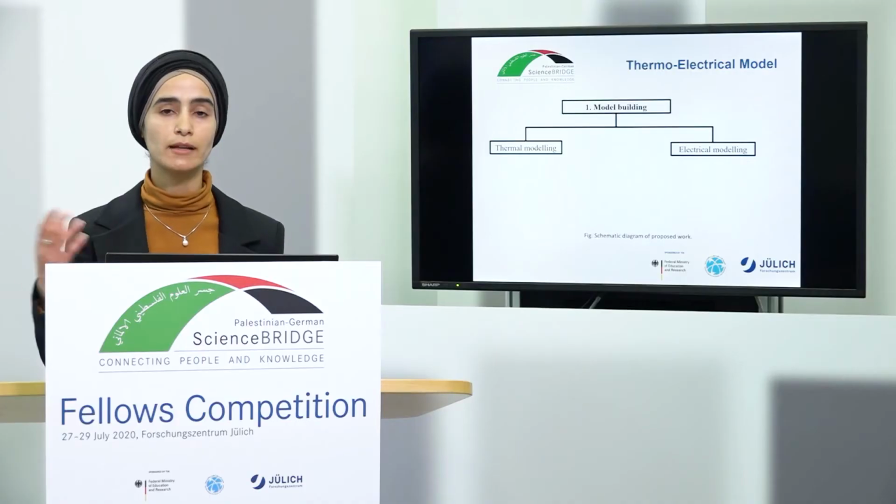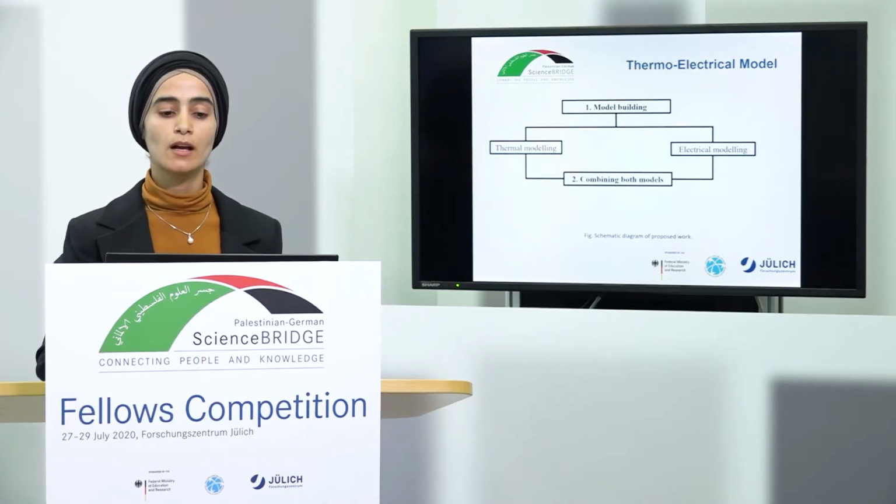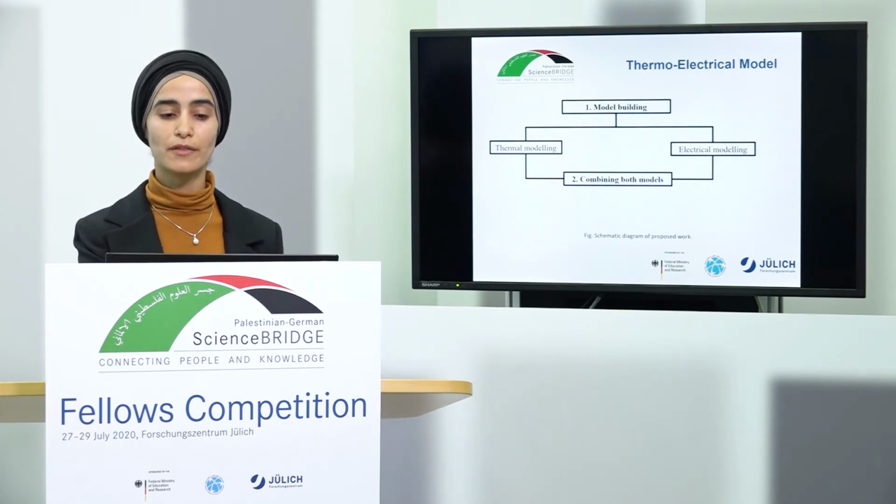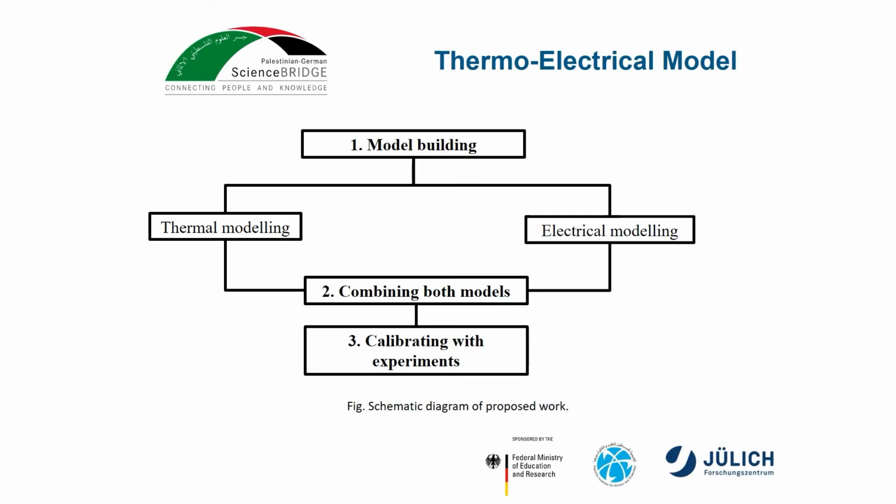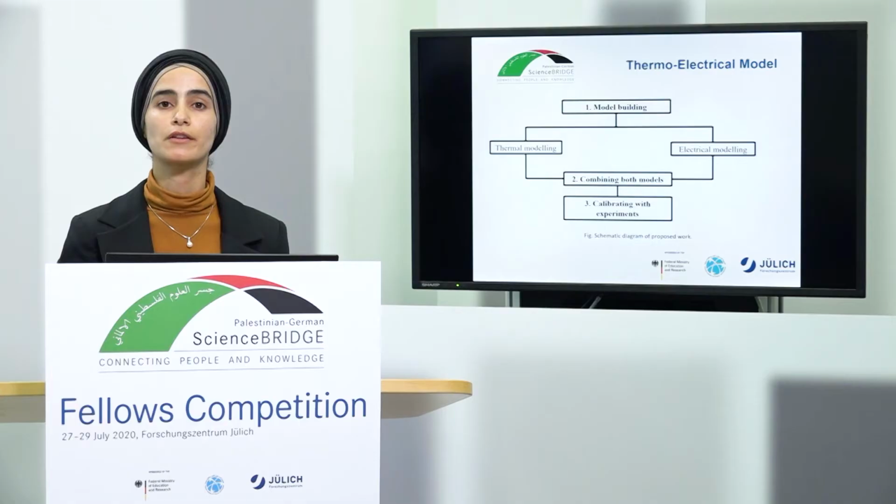So as we can see from that, both thermal and electrical aspects are strongly involved in this mechanism of formation of the hotspots. So when I say that I want to build a model, I need to build both a thermal model and an electrical model. I need to combine them together, and as with any other type of simulation, I need to calibrate and verify this model by using experiments.